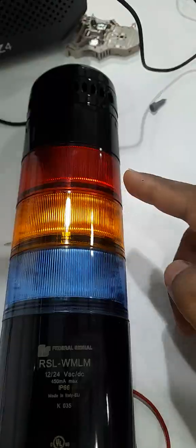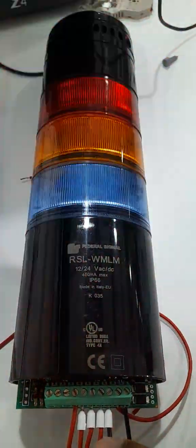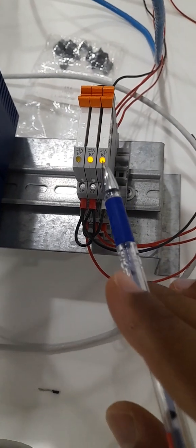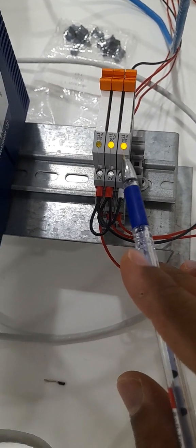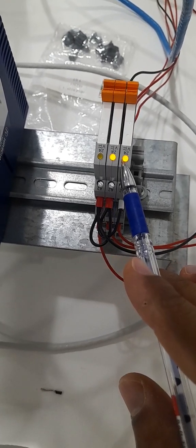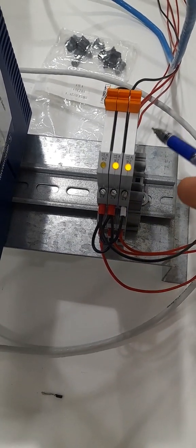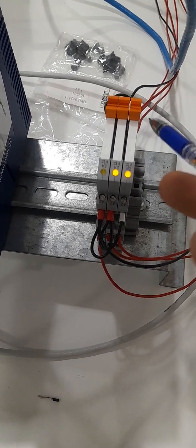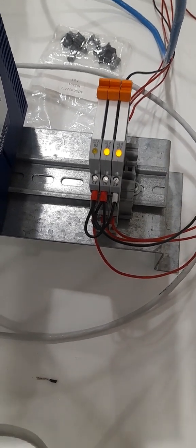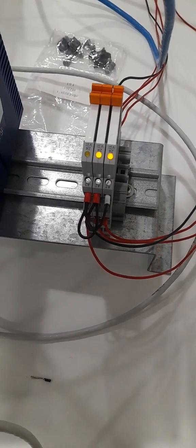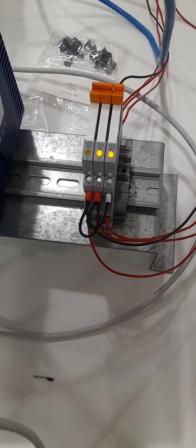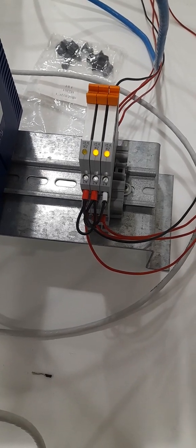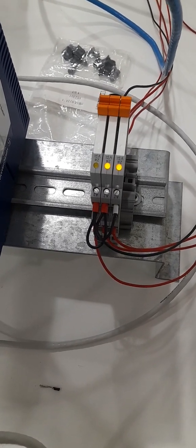Now these two lights start flashing. It means I have received a normally closed contact at terminal number 2 and terminal number 3. So you see here, these relays receive 24 volt from the PLC on priority 2 alarm and priority 3 alarm basis. In return, it makes the contact close, and on the closed contact terminals 2 and 3 receive the continuity with respect to BL, and on this continuity the normally closed contact starts flashing my orange and red lights. See here.